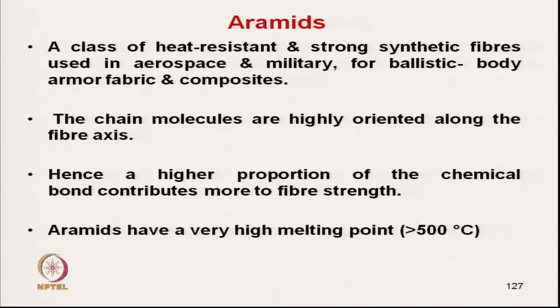This fiber is a class of heat resistant and strong synthetic fiber used in aerospace and military applications for ballistic, body armor and composite. The chain molecules are highly oriented along the fiber axis, hence a higher proportion of the chemical bond contributes more to the fiber strength.